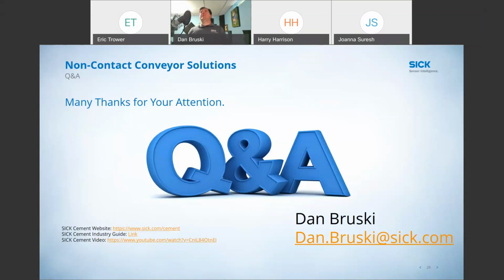I don't know if you meant just for initial setup. That would be nice, when you're right next to it. SICK is starting to put out a lot of sensors with Bluetooth, but more indoor factory automation sensors, and there's industrial Bluetooth. But as far as transmitting the data, the environments these are in, with the metal and the motors, aren't typically shielded, because we're not trying to run sensitive electronics in these environments. Bluetooth isn't going to hack it. We don't even often try to do Wi-Fi in these situations, but I could see it for a fast setup.